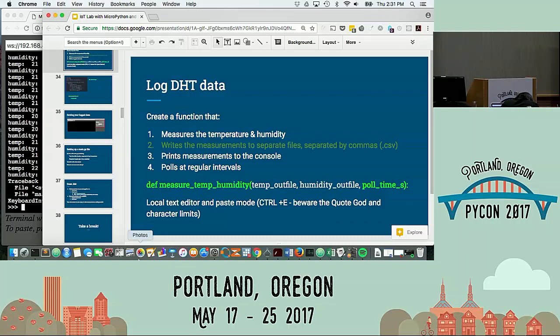This is saying that the file... or just try import DHT functions instead. Yeah, it takes a little while sometimes. That might be, check your syntax. Yeah, send DHT functions. Okay. After I import it from here, send DHT. Oh, it says name machine is not defined, so you need to add an import for machine. Okay. That's the problem.